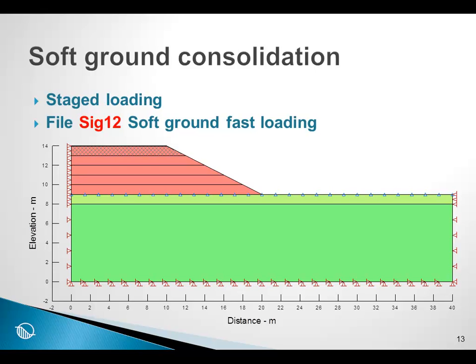We want to watch the increase in pore pressures during that time, and then in the end, when we have the peak excess pore water pressure, we want to do a stability analysis.